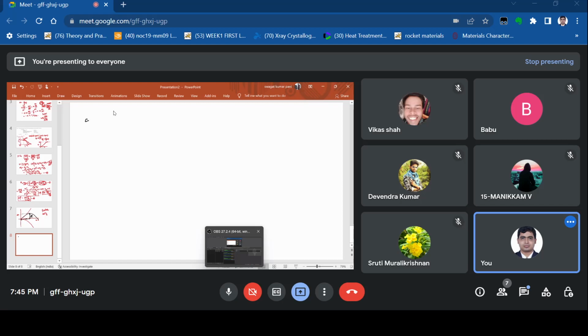Okay, so how to calculate this? As I have shown here, delta GV, what is this? First we have to calculate this delta GV, then we have to put it here in R star. So first we'll calculate delta GV, that is delta H delta T by Tm. So what is delta H here? And always remember the unit of delta GV is joules per meter cube, always.